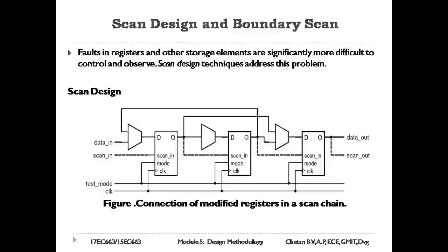Scan design and boundary scan. Faults in registers and other storage elements are significantly more difficult to control and observe. Scan design techniques address this problem. Scan design techniques involve modifying the registers to allow them to be chained into a long shift register called a scan chain, as shown in the figure.